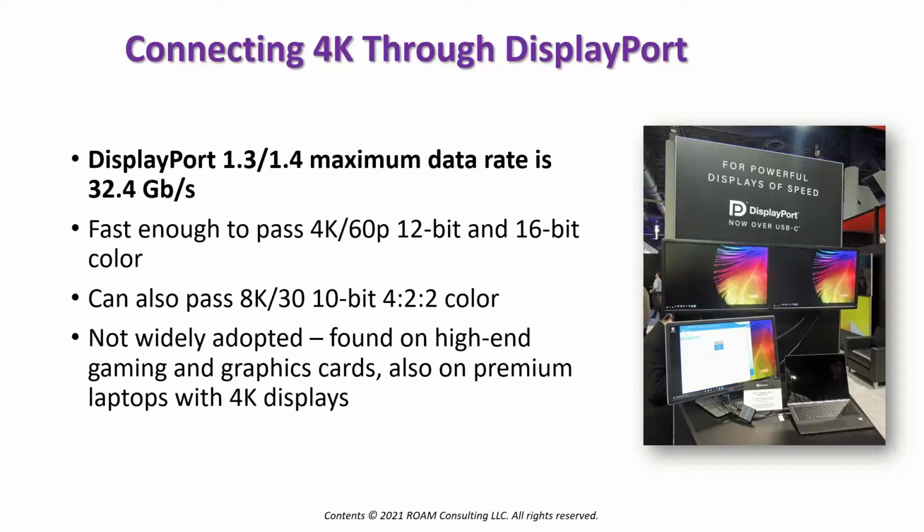And I should mention that HDMI 2.1, which is digital, is basically the same sort of thing as DisplayPort, uses the same signaling method. Both HDMI 2.1 and DisplayPort, all 1.3 and 1.4, can run something called alternate mode. And alternate mode means that you have a USB port on your computer, a USB Type-C port. That's the little one that has 24 pins on it. That can actually double as a display connection. So if you plug a computer monitor into that port, your computer will say, hey, he plugged in a display. And all of a sudden, it's now working as a display connection.